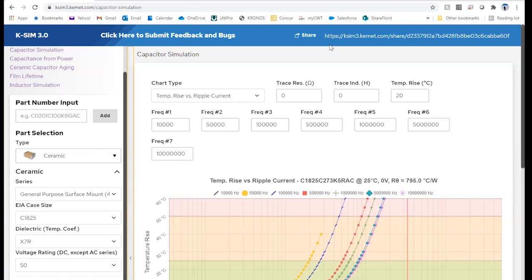But the parts do themselves like moisture. Especially when you're looking at the parts in a vacuum. Whenever they're in a vacuum, they're drained of that moisture. They're going to have charging issues, which is the anomalous charge that I'm sure a lot of military grade customers are aware of. But in general, the polymer itself does like a little bit of moisture, but it is a part that is MSL3, and you can find more information on that in the data sheet.